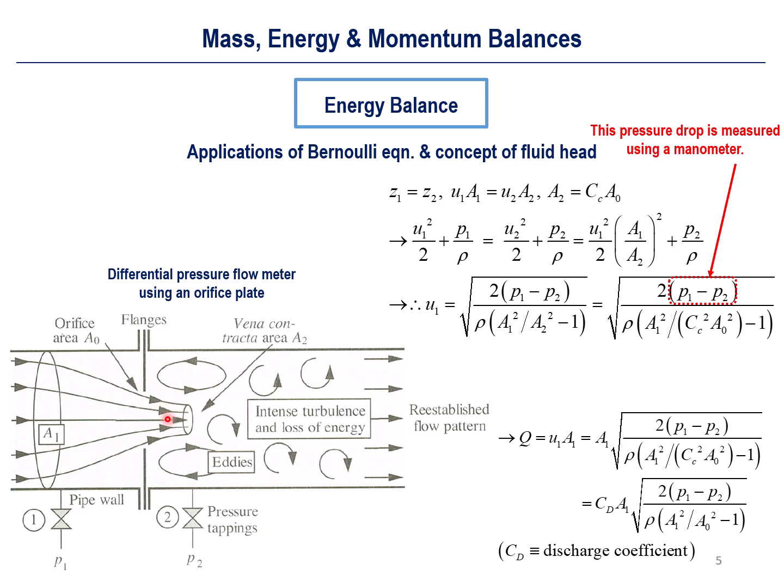So the first job is the calculation of the kinetic energy and the pressure energy, because you will have the same height. So it means that you don't need to worry about the variations of the potential energy. And we will basically assume mass conservation, and we have some contraction at the orifice, so now we will take into account the contraction coefficient. Okay, so according to the Bernoulli equation, this kinetic energy and the pressure energy should be conserved.